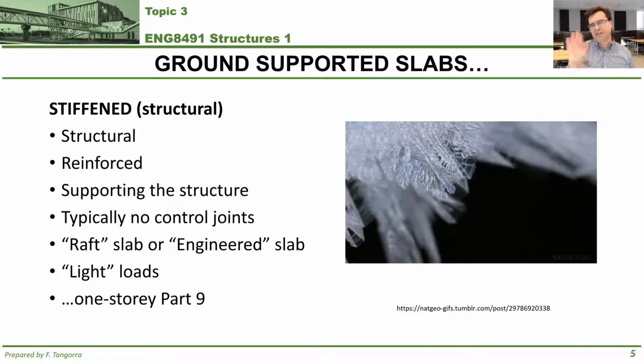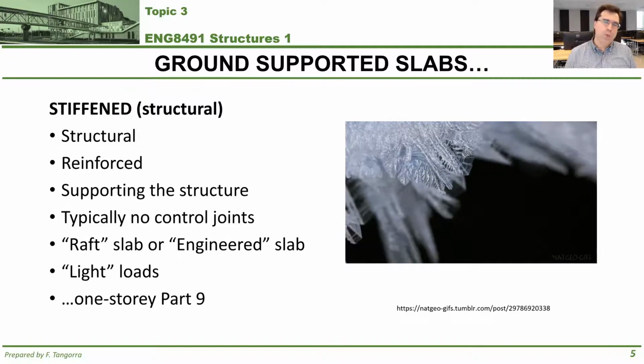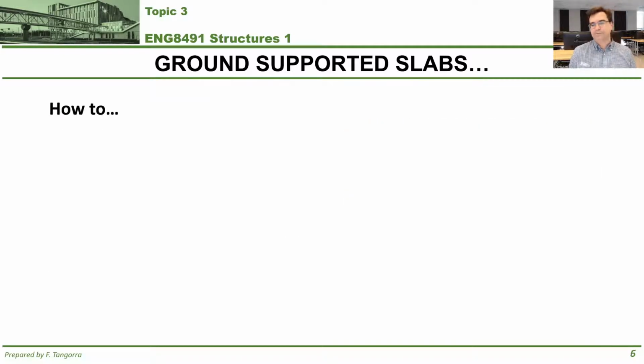So that's why typically structural slabs are not used in Canada typically for anything more than light loads. And by that I mean a one, at most, a two-story Part 9 type building, okay?